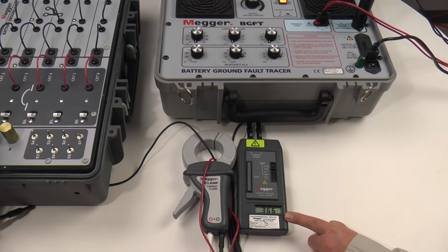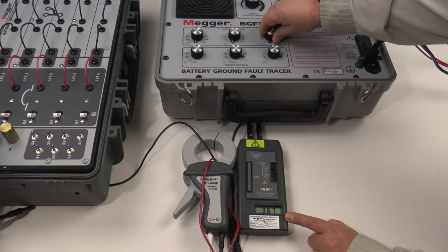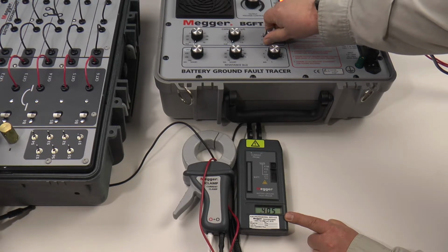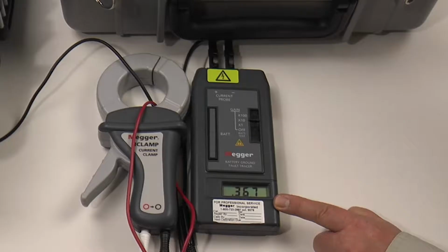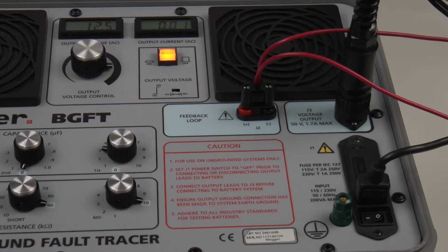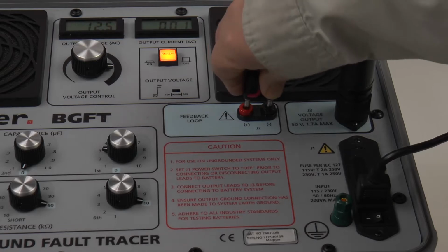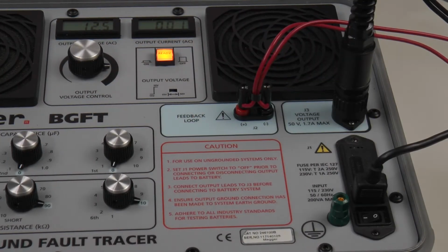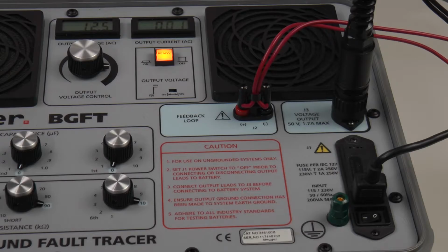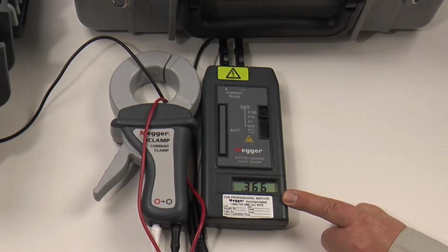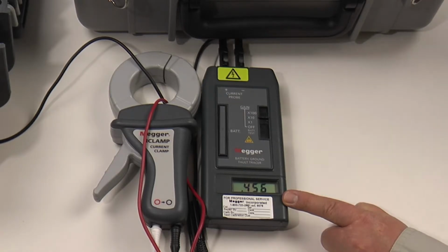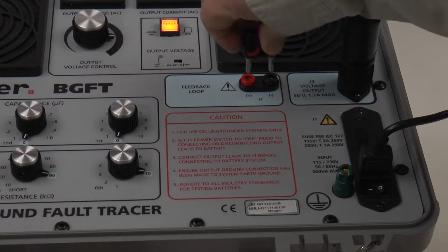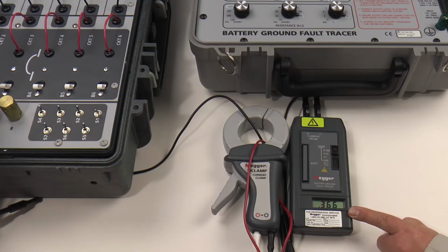While monitoring the receiver, start turning knob 1 on the Wheatstone bridge. Continue turning the knob until the reading on the receiver goes up or down. If it starts going up, stop and turn the loop around. This indicates you are adding capacitance in phase with the fault, which is drawing more fault current. If the reading on the receiver goes up no matter what direction the loop is in, this indicates there is little to no capacitance. So no matter what direction the loop is in, you are adding more capacitance, which is drawing more fault current from the transmitter.